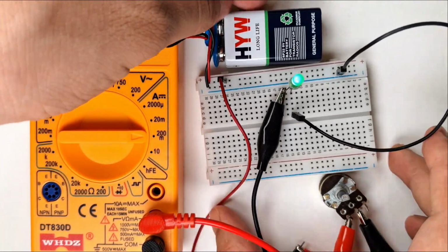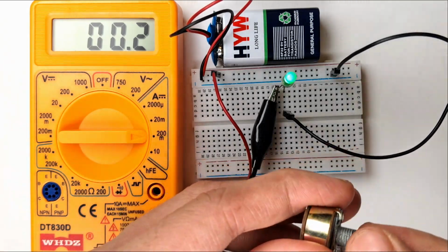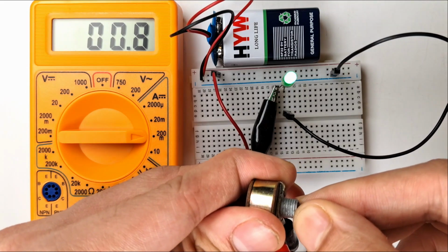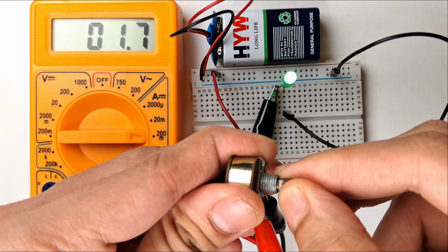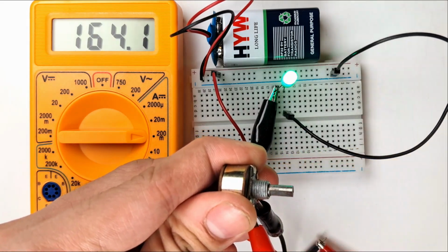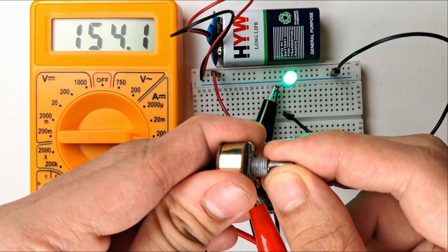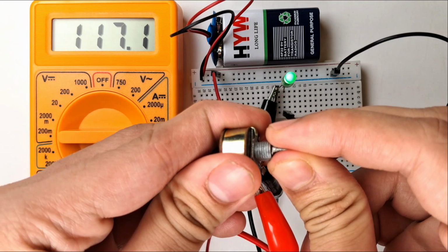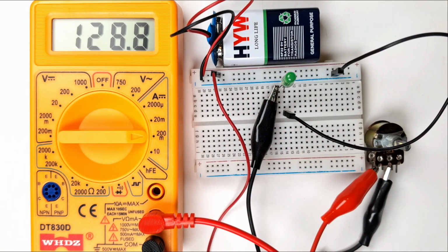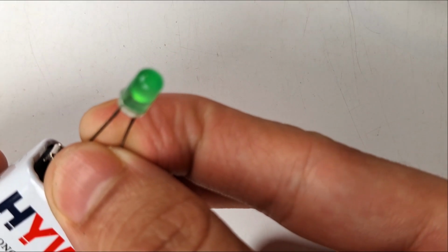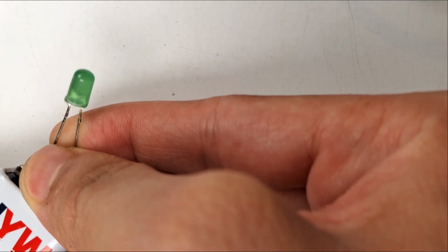This LED can handle 20 milliampere of current. If we provide more than 20 milliampere, either the LED lifespan will reduce or we will immediately destroy our LED. Let's see what will happen. Now our LED is taking too much current. Now you can see that our LED is destroyed. Now we cannot use this LED anymore. If I connect this LED directly to this 9 volt battery, the LED is also destroyed. That's why we use resistors.